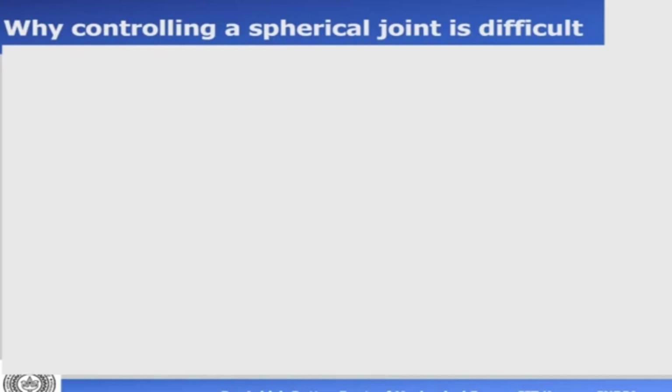Okay, but then if you look at industrial robots, 95% of them are made using revolute joints only. Now why is that so? Now if you think a little bit, if you look at the robot structure, we have a link connected by a joint, we have another link connected by a joint, and just like this. And how is the joint moved? So we have a motor. We have a motor at the back, we have an encoder, a position sensor, and we have a gear in front, and we give voltage to the motor, it rotates, and the link moves. That's how the robot moves.